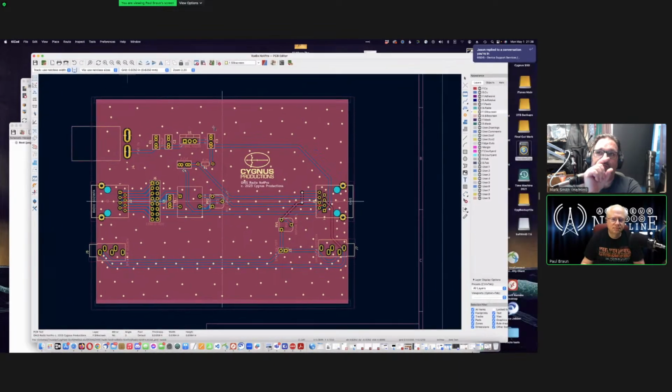Right, so you stick a reverse polarity diode across the plus 12 and ground, so that if you plug it in correctly, the diode does not conduct, but if you plug it in incorrectly, the diode does conduct, and then you make sure that there's a fuse in line. The idea being that if you reverse the polarity on the Anderson power pole, it short circuits across the 12 volts and ground and blows the fuse.